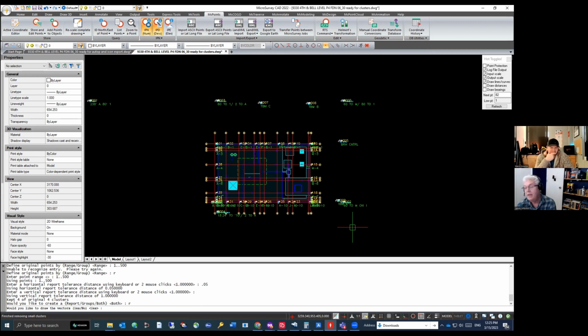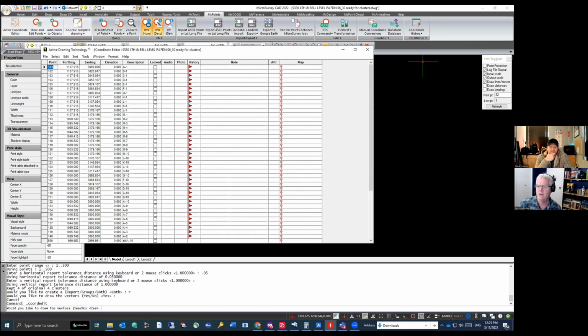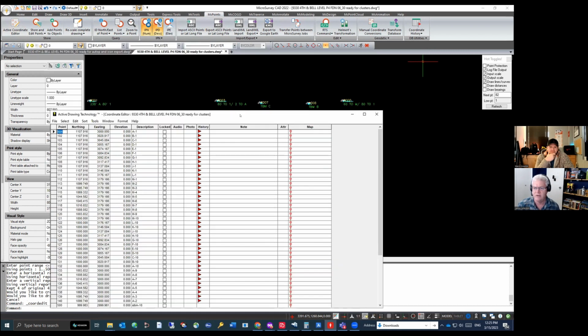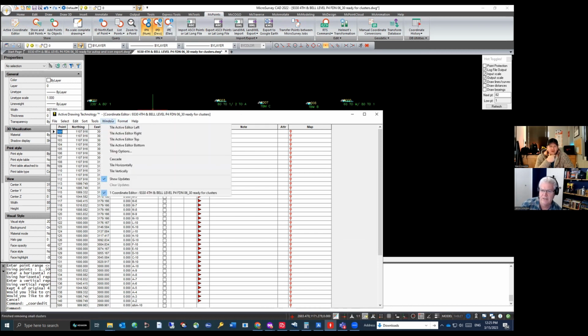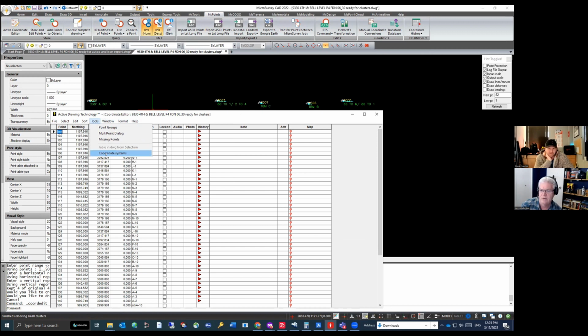Yeah, I can't demo it in this product, but Microsurvey does have all the geodetic tools that you need in the background for seeing what the ground to grid scale factor is for any point, as long as they're state plane points. Are they talking about like a localization, but post process?